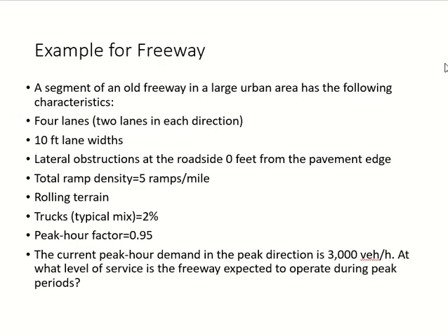Okay, you can see the reasons over here: lane width, lateral clearance, ramp density. Lane width is minimum, 10 feet is the minimum lane width. Lateral clearance, nothing, 0. Ramp density, a lot, 5 in 1 mile.